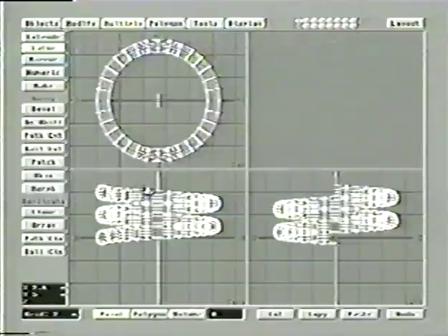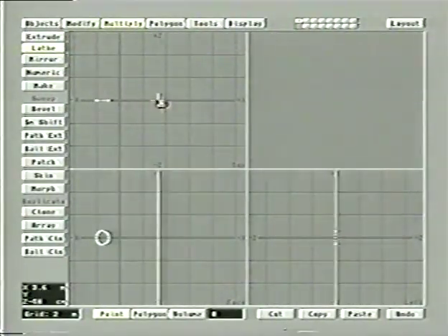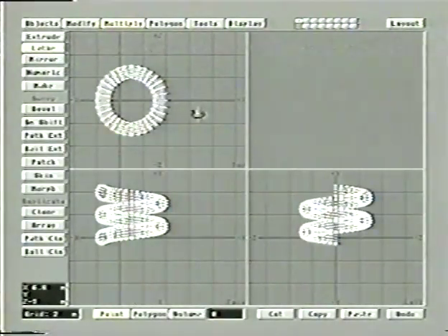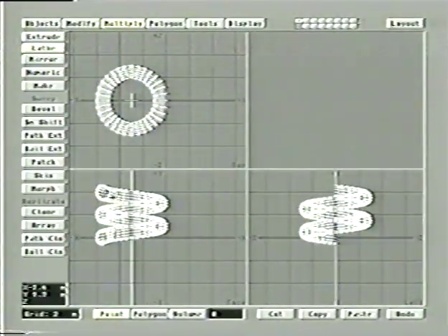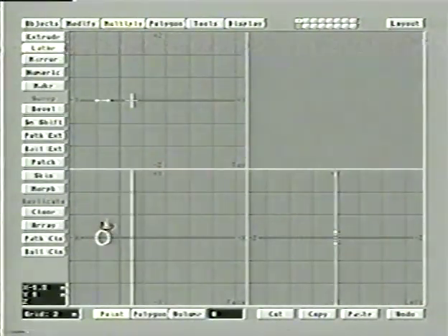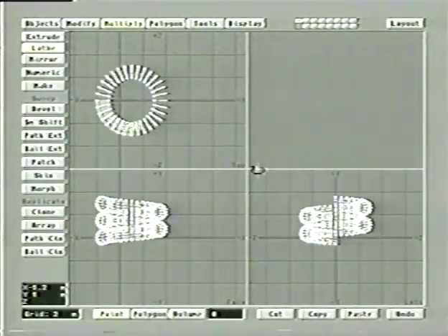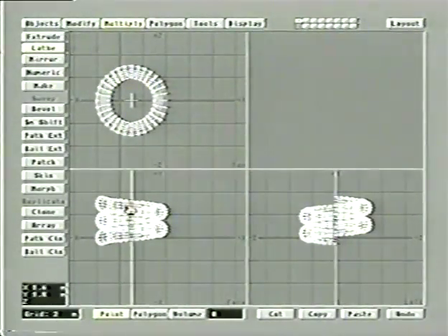So it looks a lot rounder. And if we were in fact to undo that and bring the pole in a lot closer, now you see where we can start to get that sort of spinning cord type of thing. There's a lot of things you can do with this. A coil spring, for instance. If we want the parts touching right on top of each other, it's just a matter of lowering our offset. With the offset of 4 meters, they're not quite touching. Undo, go numeric, change our offset to, let's say, 3. Now they're touching each other right there.